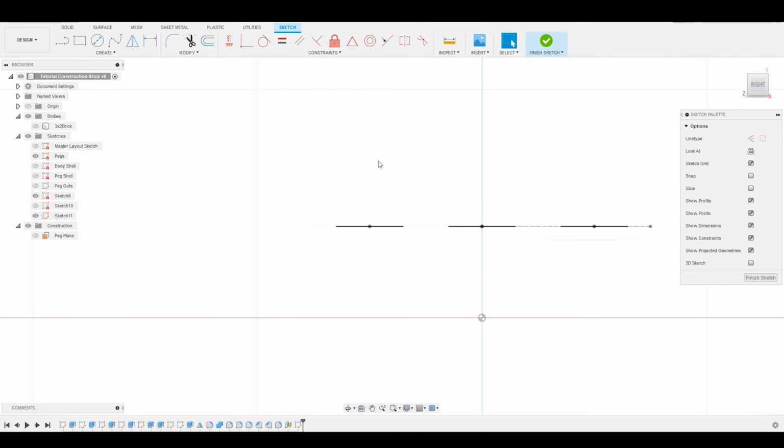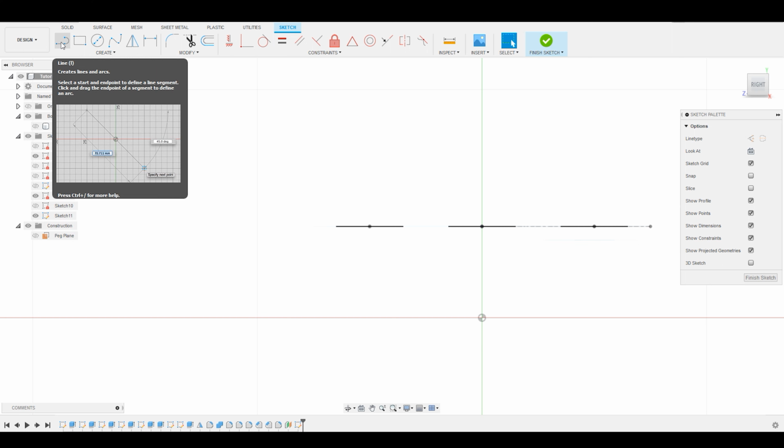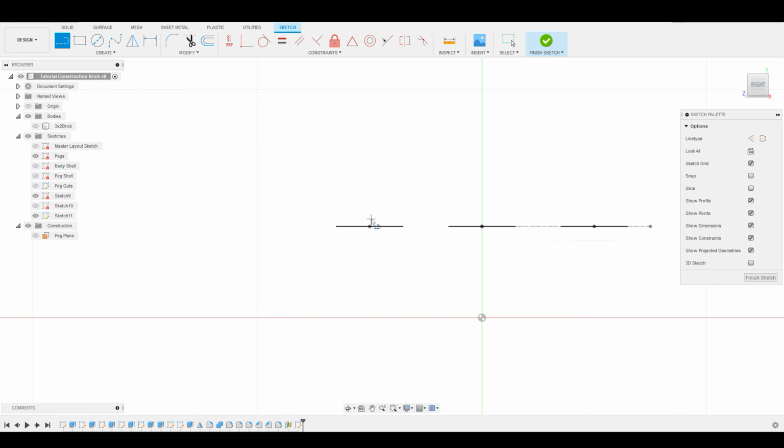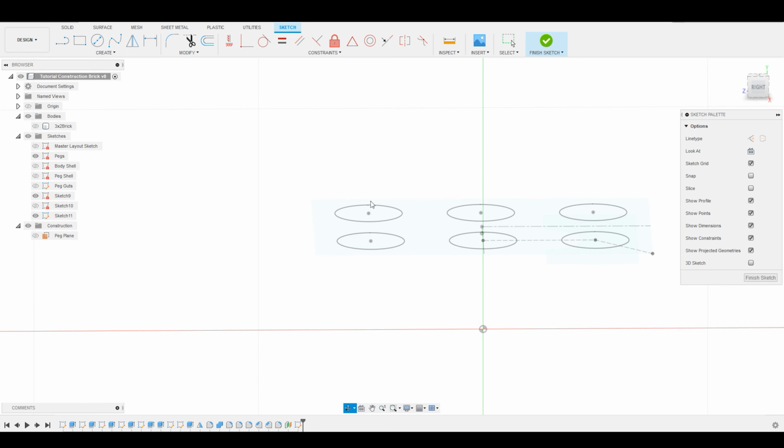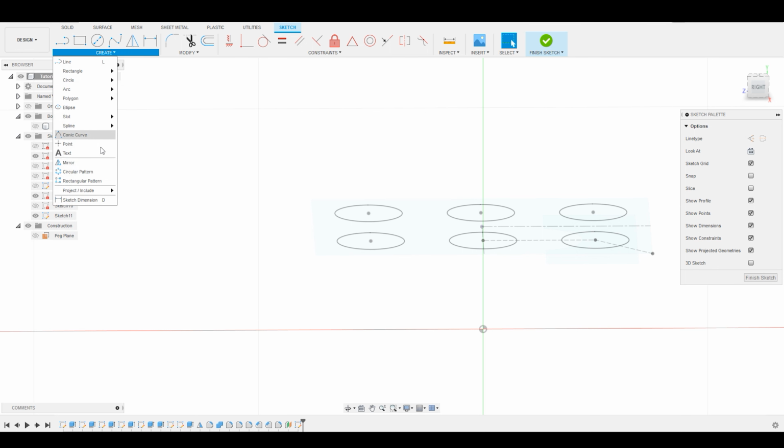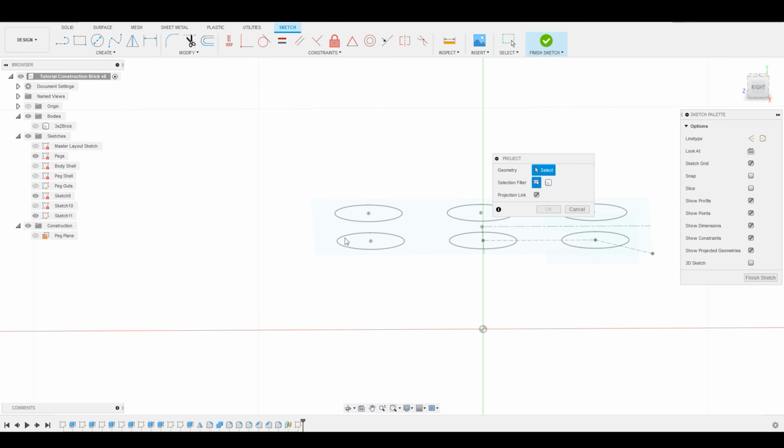All right, so now that I'm in this sketch, there are a few things that I want to create. The most important thing to create when you're going to create a revolve is the center line of the revolve. So I know where the center line is going to be, and I want to actually reference, again, this existing sketch. So I can come in here, go down to Project. We've done this a few times, and I can select just that center point and hit OK.